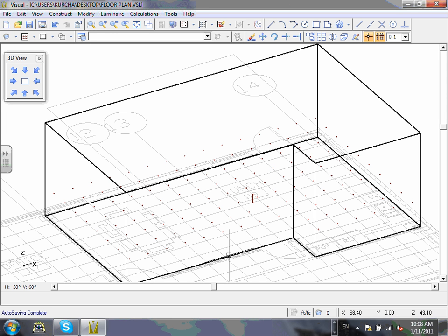If you put it at 2.5 feet and it shows at 0, then you have to go back. I think you can edit them. Can't remember. If you can't edit them, what do you do? Delete, put a new one. I think you can edit them. Okay, here's my calculation zone. That's step number 3: bring the background, build the solid, put your calculation zone for every room. The last step, guys, is to put the fixtures. We're ready to drop fixtures.